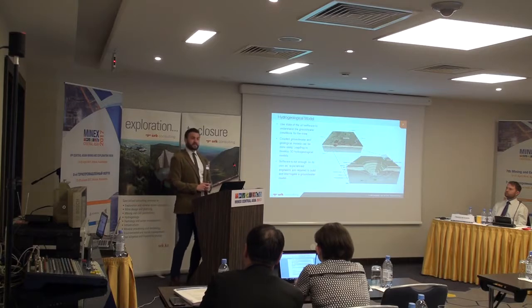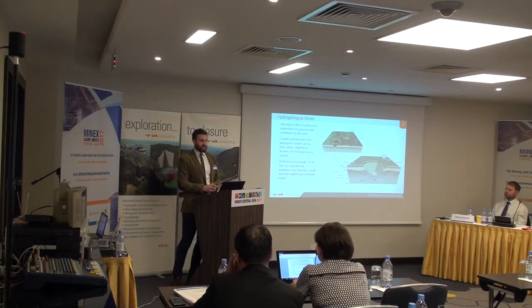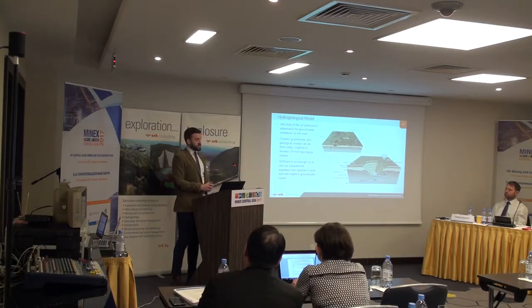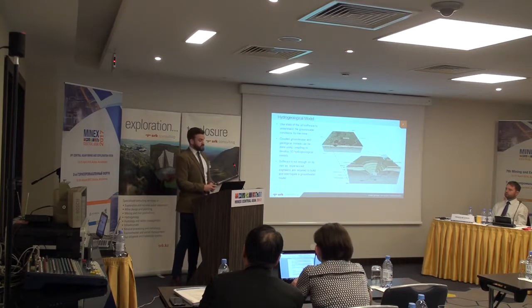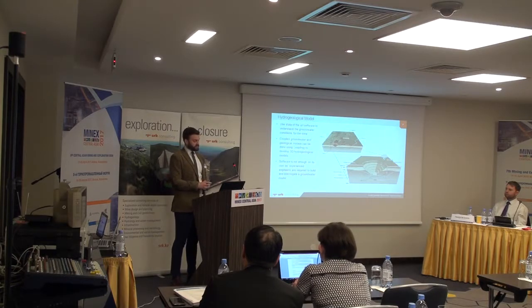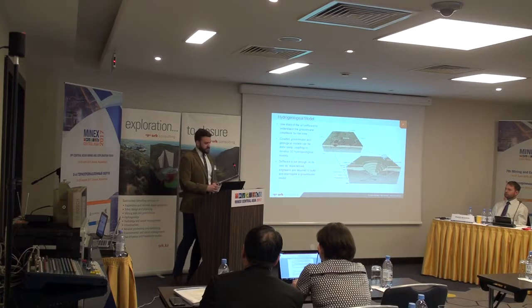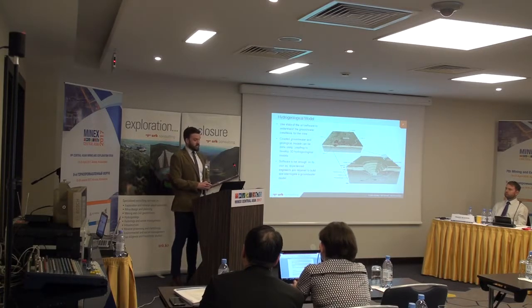And the final element to your geotechnical model is understanding the hydrogeology and the groundwater conditions. And there is state-of-the-art software available now to understand the groundwater conditions for the mine. And these can be coupled with geological models using software packages such as Leapfrog to develop a 3D hydrogeological model. And it's worth pointing out here that software is not enough on its own, as experienced engineers are required to build and interrogate a groundwater model.